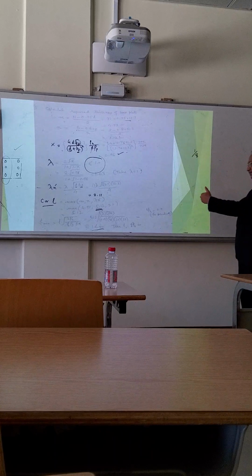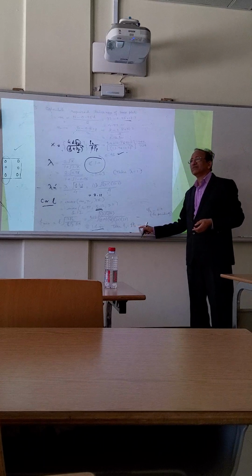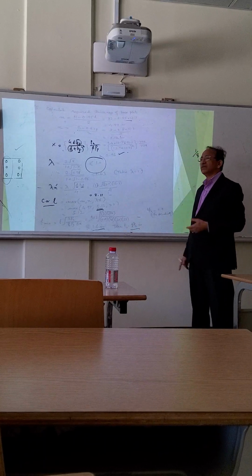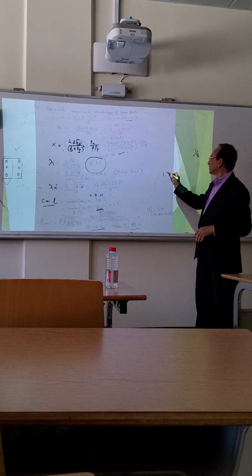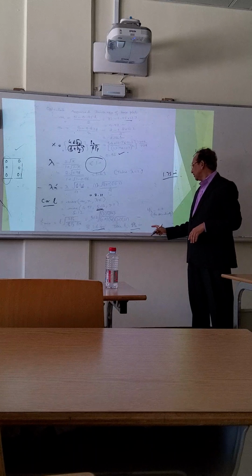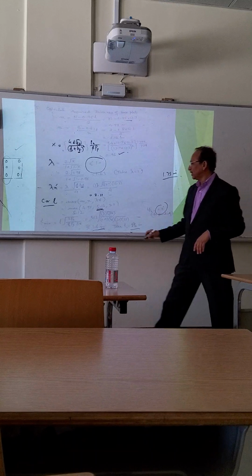So according to that, you decide it should be 1 and 3 by 4, that means 1.75 inch. This will be the value, and phi for the bending case will be taken as 0.9.